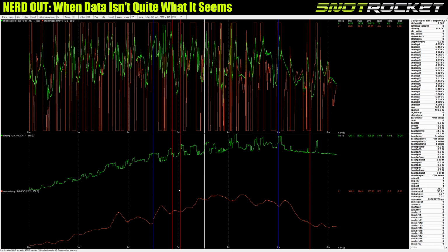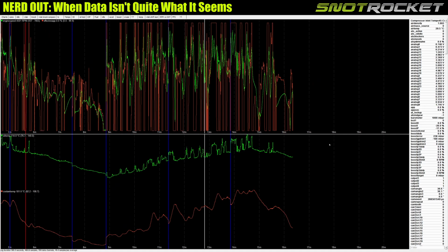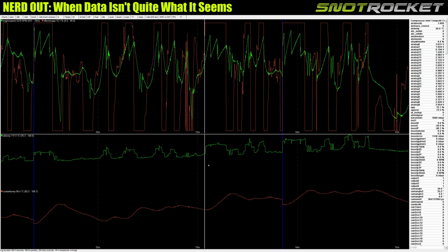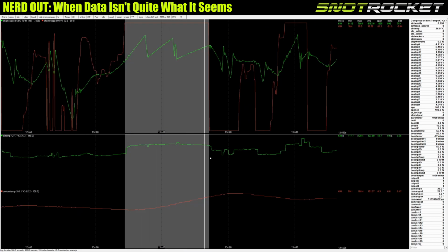So I was trying to see, well, what's influencing? What are the common patterns here with these spikes in the oil temperature, right? So you can see up here on the second stint, the changes are quite significant. So I thought, what's the common issues? If I take this spike here, this is an obvious spike, between this point and that point. And then when you look up at the engine speed, you can see that's going through probably 4th, 5th and 6th gear, up to about 125 miles an hour, I guess, by the end of where we are here.